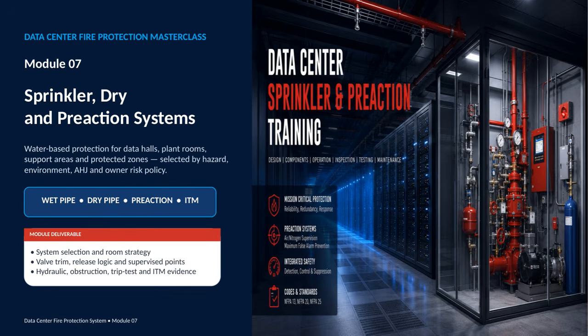We'll also examine the details that make a system dependable in service, including valve trim, release logic, and supervised points. Finally, we'll consider the evidence needed to demonstrate performance and readiness: hydraulic information, obstruction checks, trip testing and inspection, testing, and maintenance records. By the end of the module, the goal is a clear, defensible approach to choosing and supporting water-based fire protection for different data center spaces.